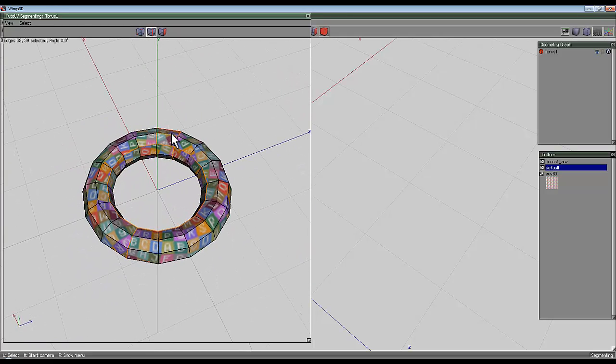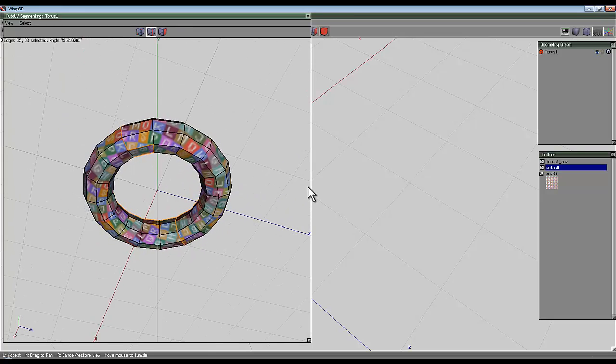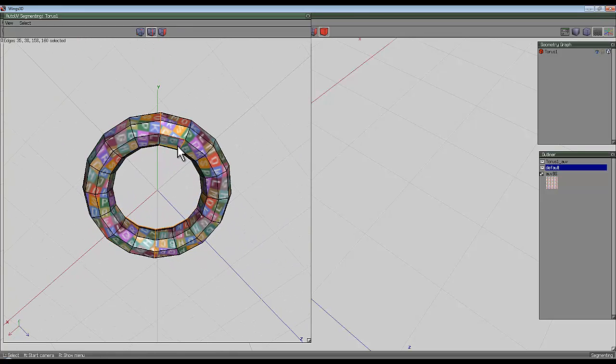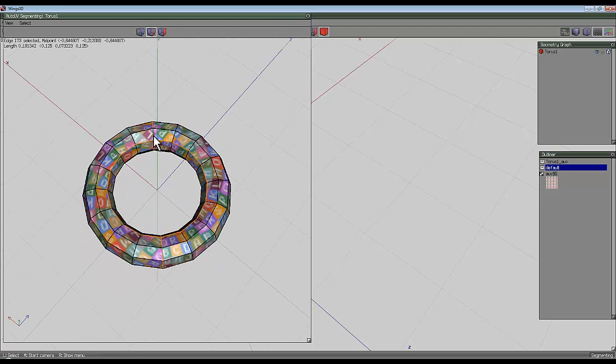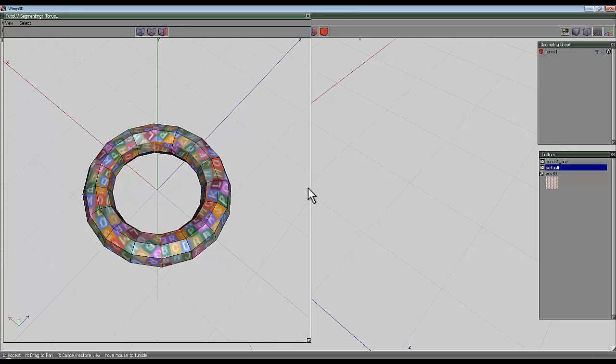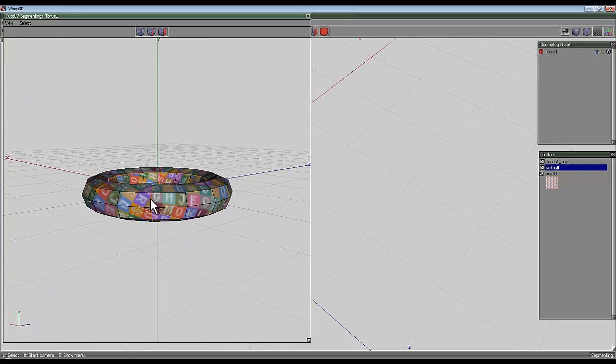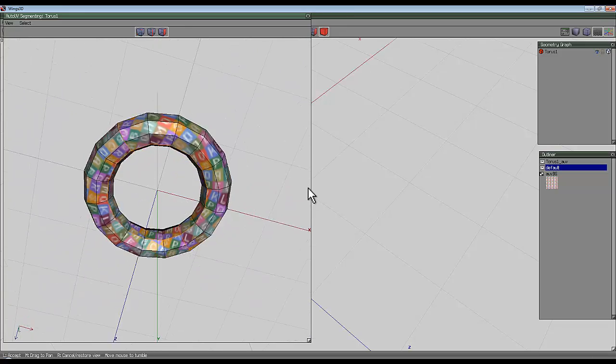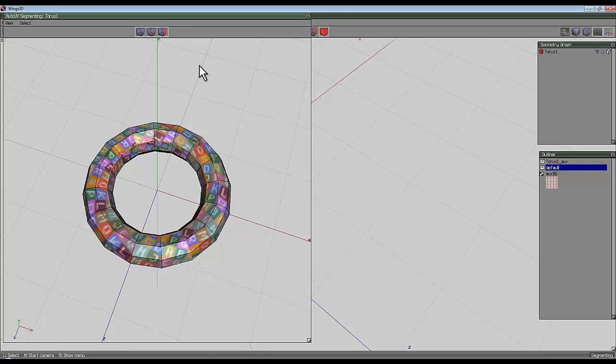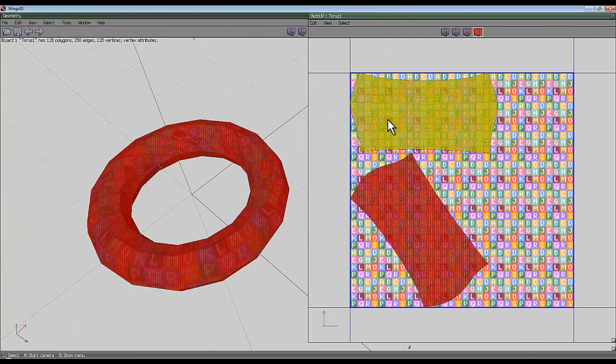So I'll unmark these oddments for cutting. So just unmark those edges, press space, go back to edge, and then I'll make sure I've got a cut there, and mark those edges for cut. Now they've been done, I can see I've got a cut all the way around that side, a cut around that side, and a cut along that top edge there. So we'll continue by unfolding.